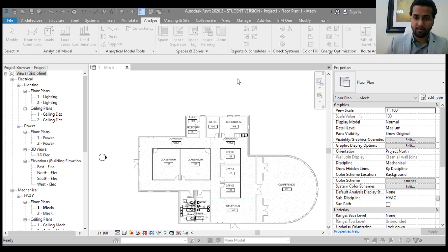Similarly, the area, let's click here. Let's say this is based on area of the room. So area can be different because you don't want to see it based on values like this. Okay, let's say I want to give a range of values like from 1 meter to 10 meter. I want to add all those spaces into one single color. So you can give by range option here, and you'll find that now you have 0 to 20 and so on. So you can add various ranges here. Okay, you can see we can add as much as you want based on the larger area, and if you want, you can also modify the colors provided here.